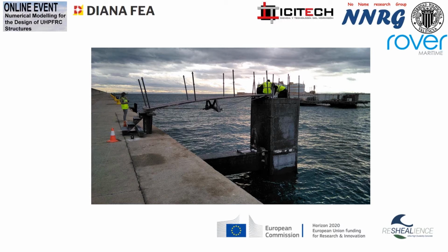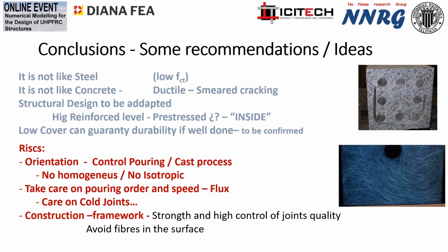Okay, then at this moment it is there, with lots of sensors to analyze corrosion. You can think that those elements have rebar with only 2 centimeters, 15 to 20 millimeters of cover in some parts. And we are controlling, minute by minute, the initiation of corrosion, which of course does not happen at the moment. We control the crack appearance, and the idea with that is that this is a different material. You need to think as steel, but you need to design as concrete.